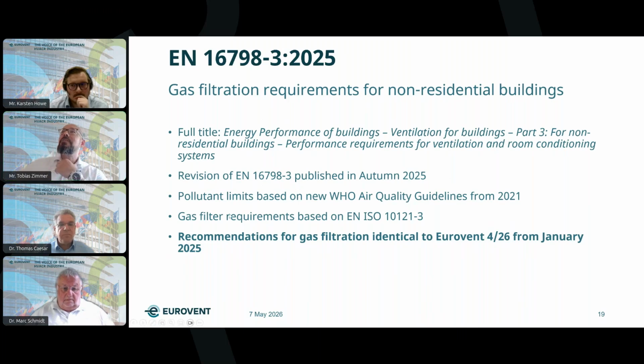So what does it do? It bases the gas filter requirements on ISO 10121-3. It puts pollutant limits based on the WHO guideline. That's exactly the limits that Karsten showed earlier. And then it gives you a recommendation which filter to use in which application.